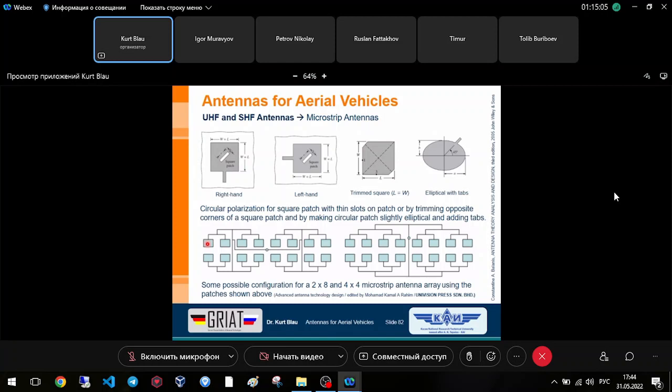It's fed by this microstrip line here and here, and here and here. This means we have on the left side 4 such subgroups consisting of 2 elements combined with this line. Then the next plane of combination of the elements is this here. We connect or feed together these 2 subgroups with this line here and here. And the next plane is this one.